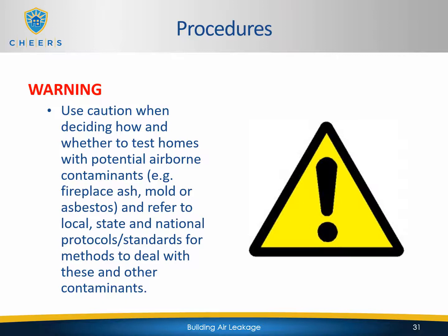Warning: use caution when deciding how and whether to test homes with potential airborne contaminants, for example, fireplace ash, mold, or asbestos, and refer to local, state, and national protocol standards for methods to deal with these and other contaminants. Always do a walk around of the house and a quick assessment to make sure that there are no potential dangers that you're going to be bringing into the house or creating for the homeowner before starting the blower door.